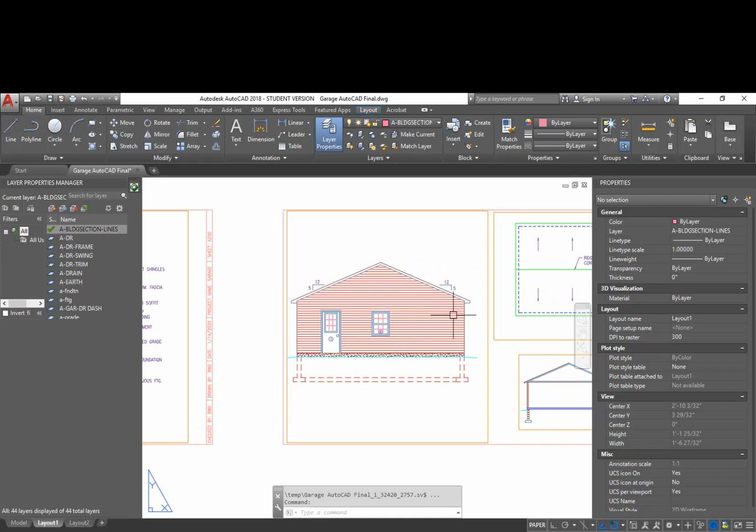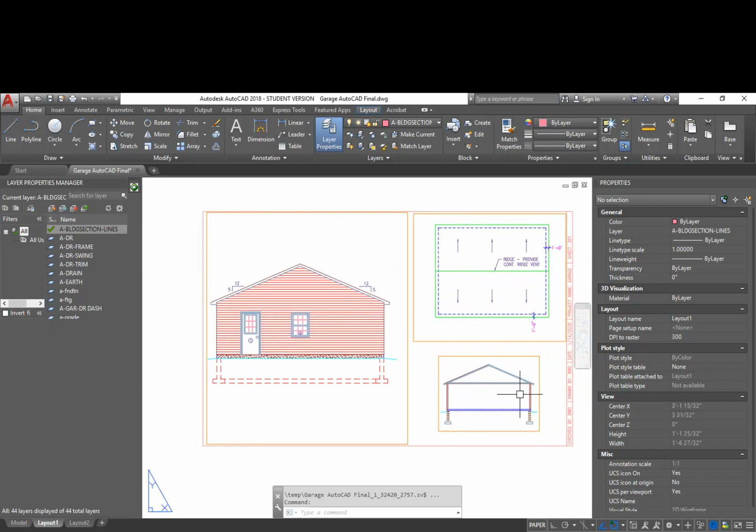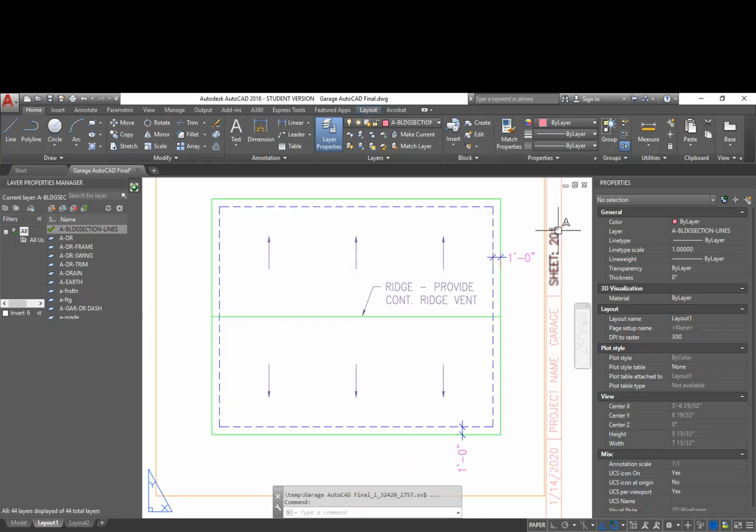Our second elevation is also going to contain a roof plan and a building section. Now technically what we'd normally do is our elevations are going to be a 200 series, our floor plans are going to be a 100 series, our sections are going to be 300 series, and then we have the 100 designation so that we can continue. We could basically have 99 different floor plans, or 99 different elevations within this, and it makes it real easy to add additional drawings in later on, because instead of having to renumber everything,